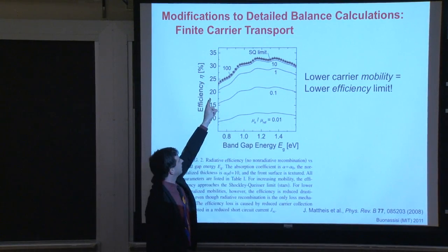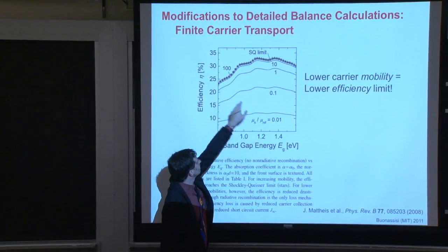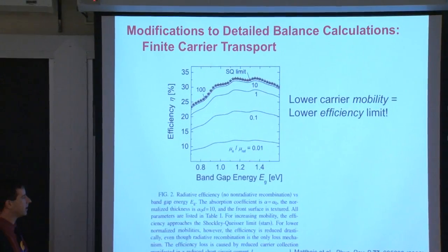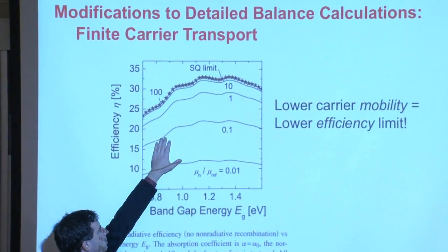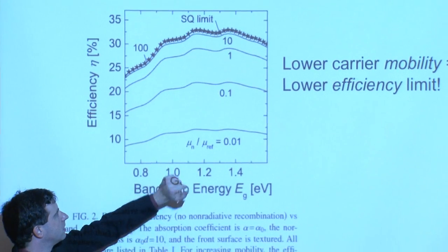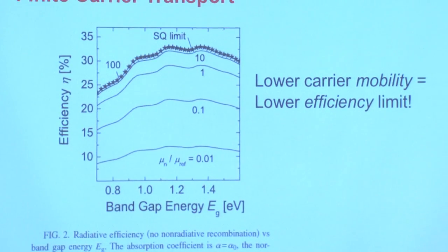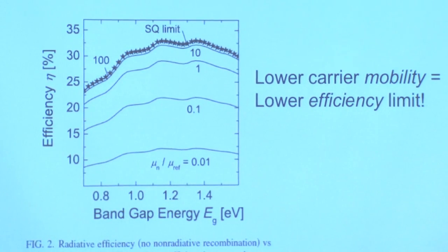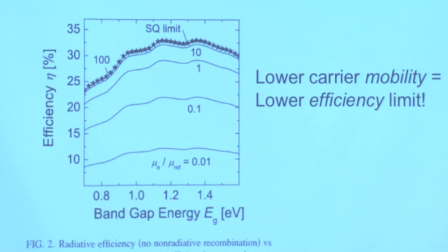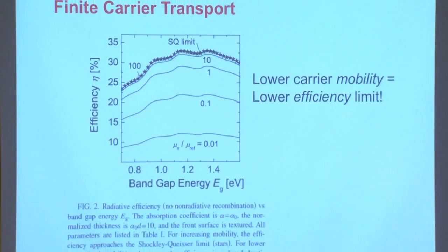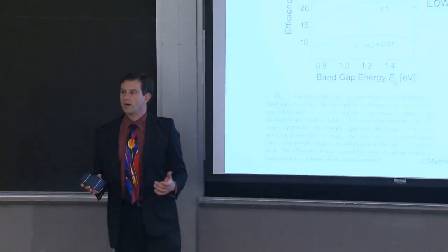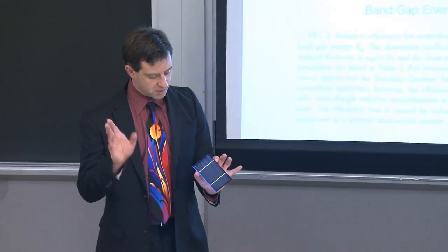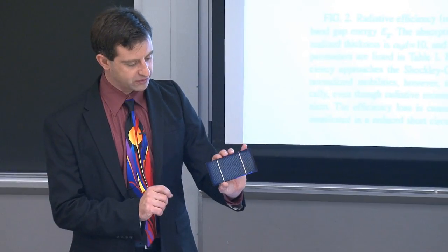And you can see, number 1, that curve that's starting here at the 20, that is for a mobility that is close to the optimal. If you drop by an order of magnitude or 2 orders of magnitude relative to, say, the maximum mobility inside of a material, your performance begins to degrade considerably. And now you can understand why crystalline silicon, which has electron or hole mobilities somewhere in the range of a few hundreds of centimeters squared per volt second. So keep that number in your mind, on the order of hundreds of centimeters squared per volt second hole mobility.